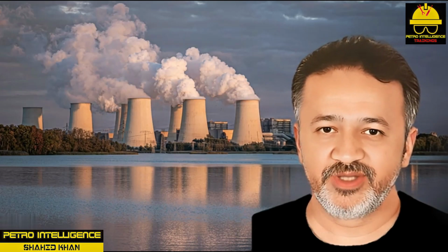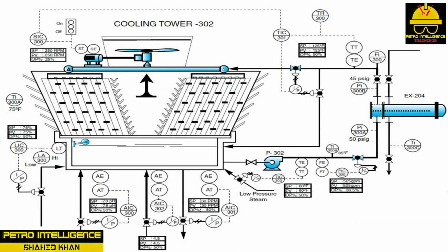Pump 302 failure. If pump 302 fails, the distillation system will immediately go into alarm condition. The pump backup system will need to be placed online immediately. P302 is a vertically mounted centrifugal pump with a series of small screens installed on the suction side of the pump. These screens keep the liquid entering the pump clean and prevent internal damage.